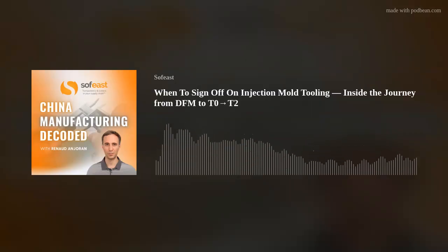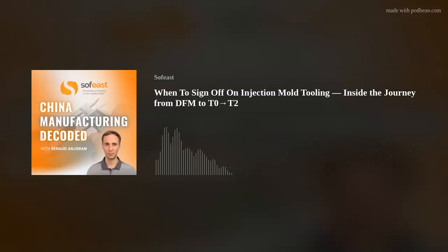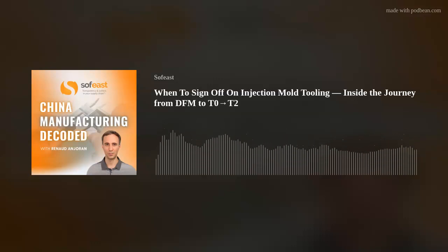You need to get more than one component sent over. Say get 2 or 3 of each part sent to you, so you've got a variability from a color point of view. Well, hopefully not too much variability, but you've got something to compare. Get your black marker pen out, sign it, or mark up what's not acceptable. Because this is what's needed, even if this is no good because it's got too many black dots or too many scratches or too many defects in one particular area.